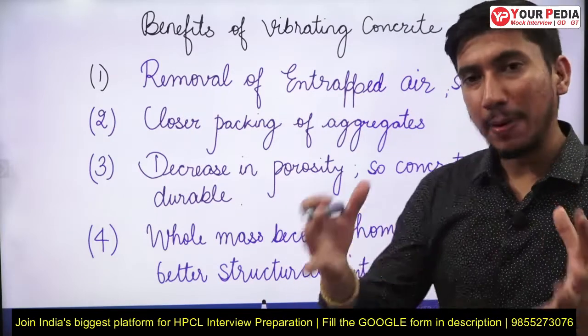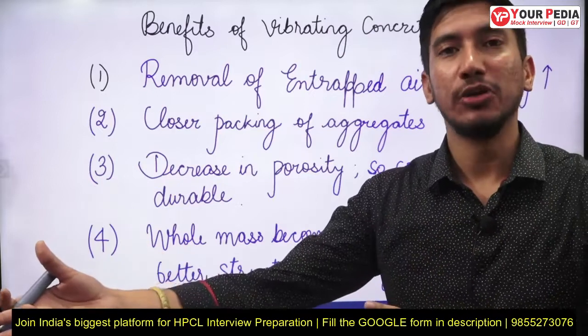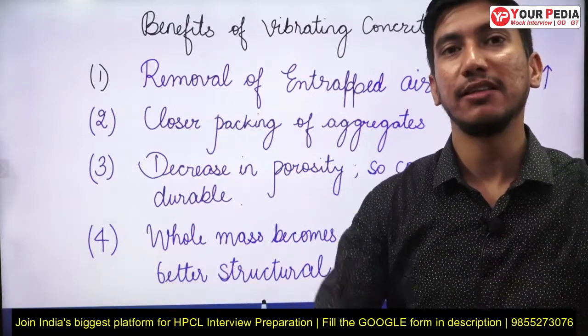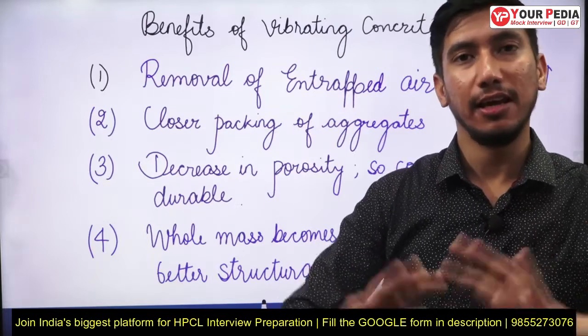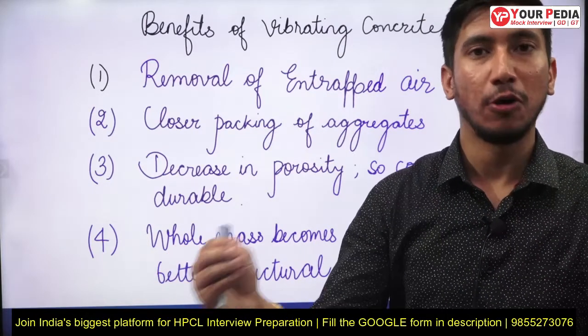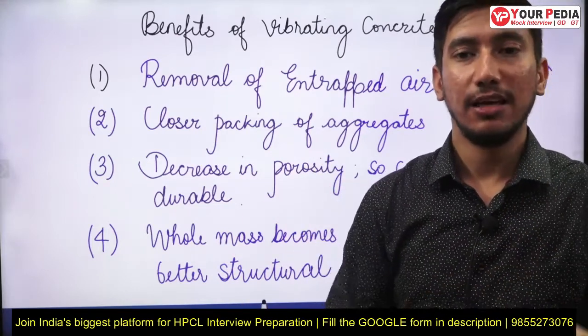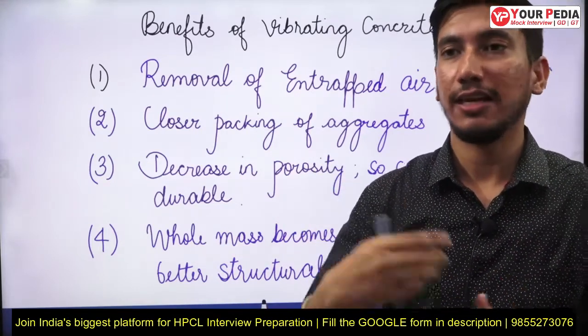Okay, so compacting concrete is like compacting soil. In sandy soil also we apply vibroflotation. We vibrate the sandy soil. What happens is air escapes from the voids and the grains arrange themselves in a closer packing. Now this sand is better in resisting dynamic loading.